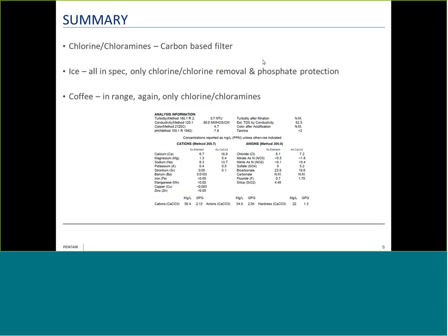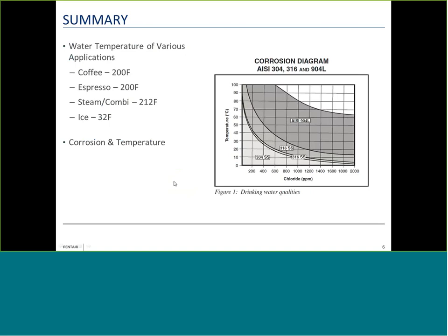And then there's the other indices that we use to determine what the water is going to do and what issues it is going to create. And I had mentioned LSI before. Well, LSI, it is the Langelier Saturation Index, and it's an accurate gauge of whether the water will precipitate or cause scale to form, calcium carbonate specifically, or dissolve that calcium carbonate off the walls of the plumbing or boiling chamber.